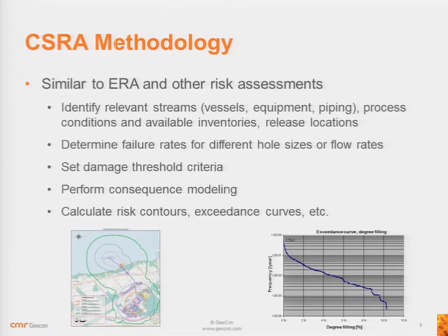Here we're not looking at overpressures. We're not looking at ignition of this. We're looking at actually when it doesn't get ignited, when it stays cold. So typical examples are temperatures in the order of -30 to -40 degrees C, when embrittlement becomes possible for non-cryogenic steel. And then you have your scenarios.